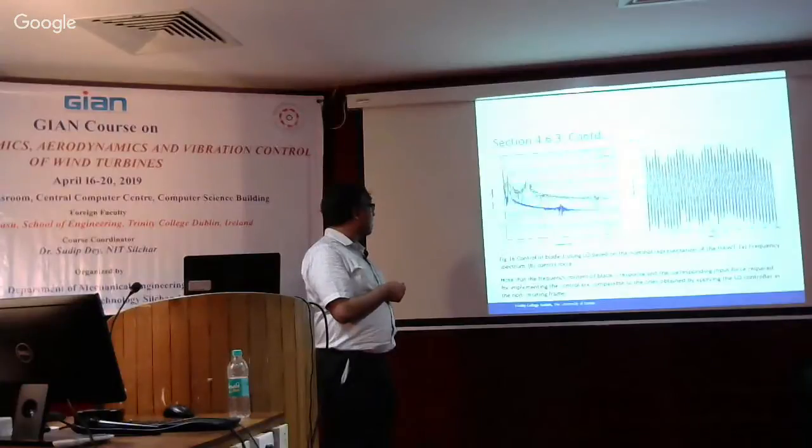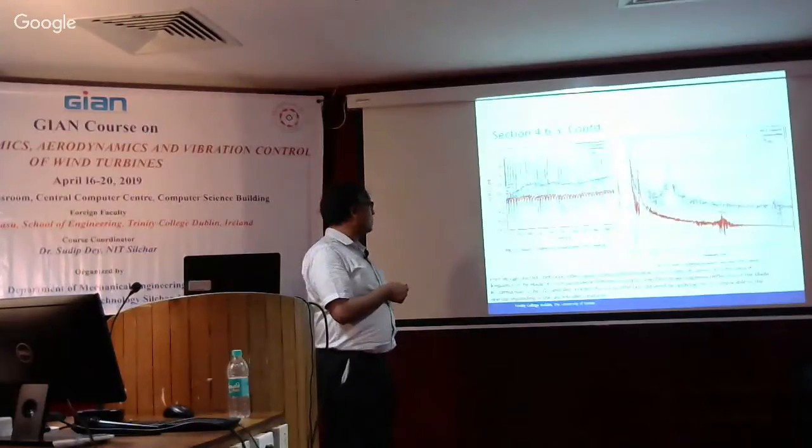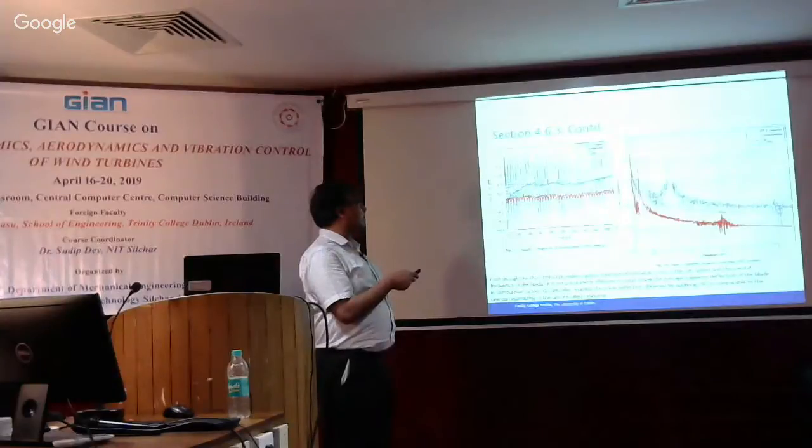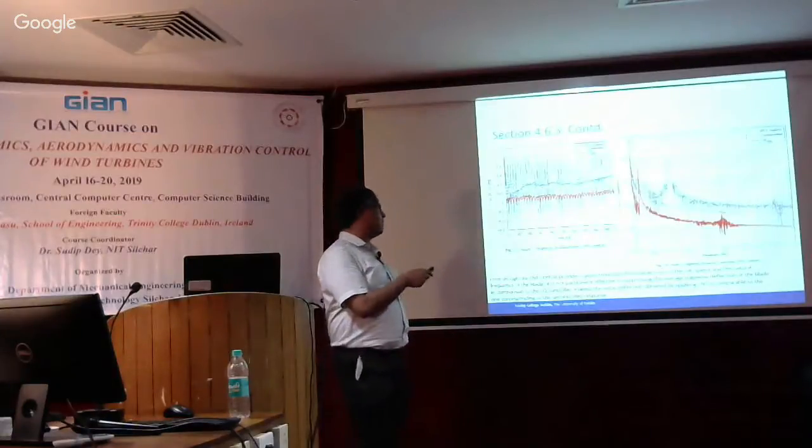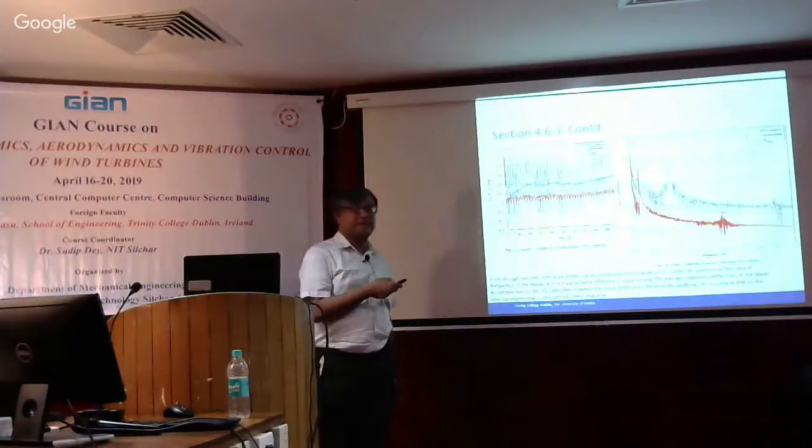And this again, the nominal controller. Yeah, so this is the direct velocity feedback. See, the direct velocity feedback is also able to suppress the vibration, the response. What happens is you actually have a non-zero mean value in the direct velocity feedback. That shows up over here in low frequency. That is completely suppressed by the controller we had here.